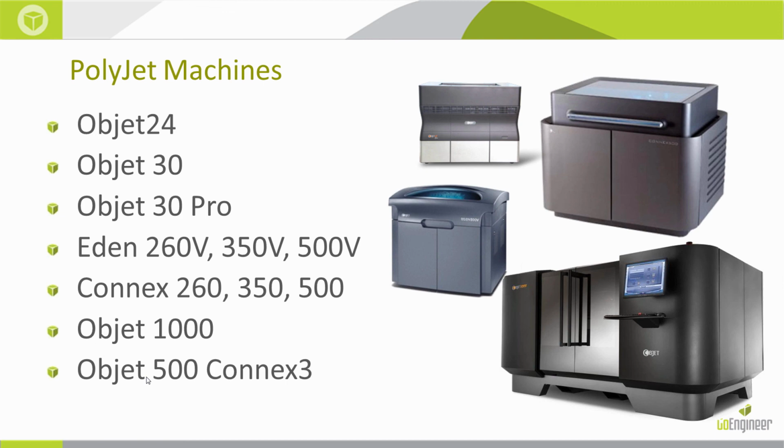The Connex 260, 350, and 500 are very similar to the Eden machines. They have all the same material capabilities plus one. They can print the digital ABS, and the reason they can print the digital ABS and the Eden machines can't is because the Connex machines have 2 print heads. So they can print 2 materials at the same time. The digital ABS requires 2 materials to print. They're mixed together at the time of printing. But this also means we can print a character like we saw at the beginning, that halo character, with some rigid hard materials and some rubber-like materials all in a single print.